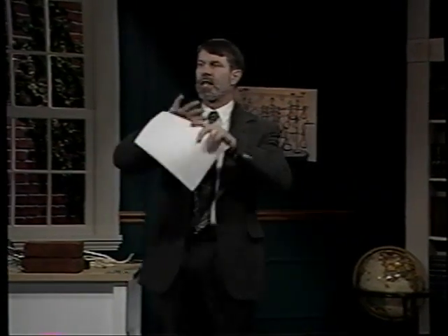One thing you may have noticed is how minor defects in a material can greatly reduce its strength. A classic example is glass. You have the slightest scratch or nick on a surface of glass, and that can start a crack that will destroy a whole piece of glass. For example, your car windshield. And you may have seen that. You get a tiny scratch, a tiny crack, and it will propagate, weakening the entire glass structure.